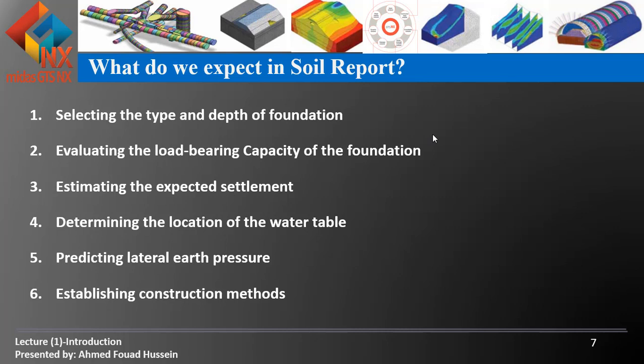We have to create a lithology of the boreholes we had, and we create a section about the stratification of the soil through the soil layers. Then we have to evaluate the bearing capacity of the foundation. If we have a foundation, we have to see how much stress the soil can endure. So we call this load bearing capacity.